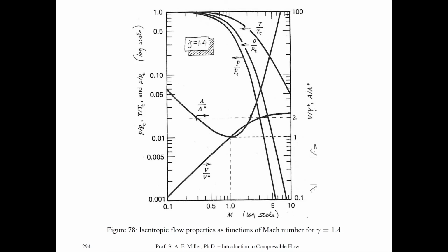However, the velocity at the throat is equal to the speed of sound. So we could also write u over c star if we so desired, because u star equals c star, because M equals 1 at the throat only. Once again, remember that c over c star will certainly vary as a function of Mach number, because c is mainly a function of temperature T, which you can see varying. Can you try and draw the graph of how c over c star varies with Mach number?